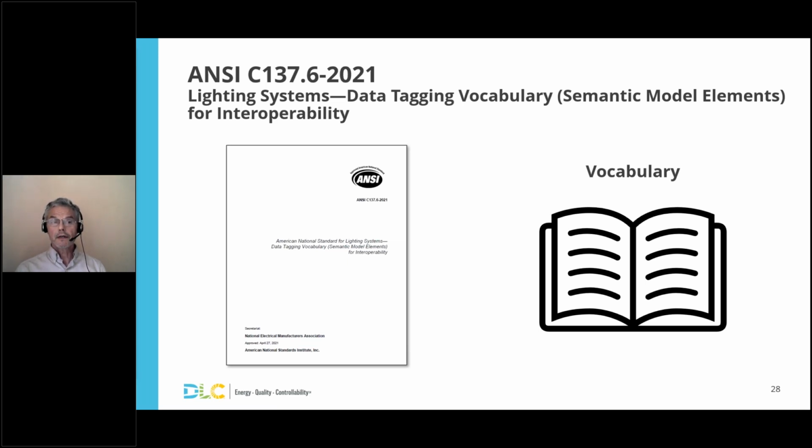The terms that are included support real-time interoperability for two different lighting control systems that need to work together. For instance, when the lights in two different wings of a building are controlled by NLC products from two different vendors. This is relevant here because terms for exchanging energy data are included. This will support energy reports for energy efficiency programs and also support real-time energy dashboards.